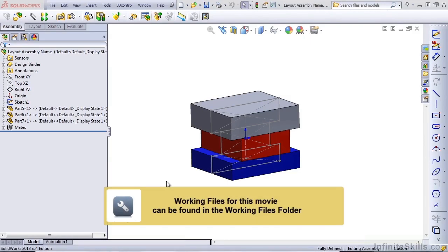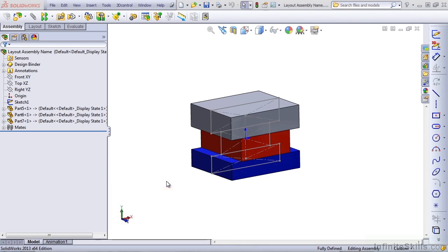In this lesson, we're going to continue with top-down and layout techniques. I'm going to start with creating a new sketch in the layout to drive holes in this assembly. These holes will be for mounting holes. I've got 3 plates, so the top plate will have to get a counterbore hole, the mid plate will get a clearance hole, and the bottom plate will get a threaded hole.